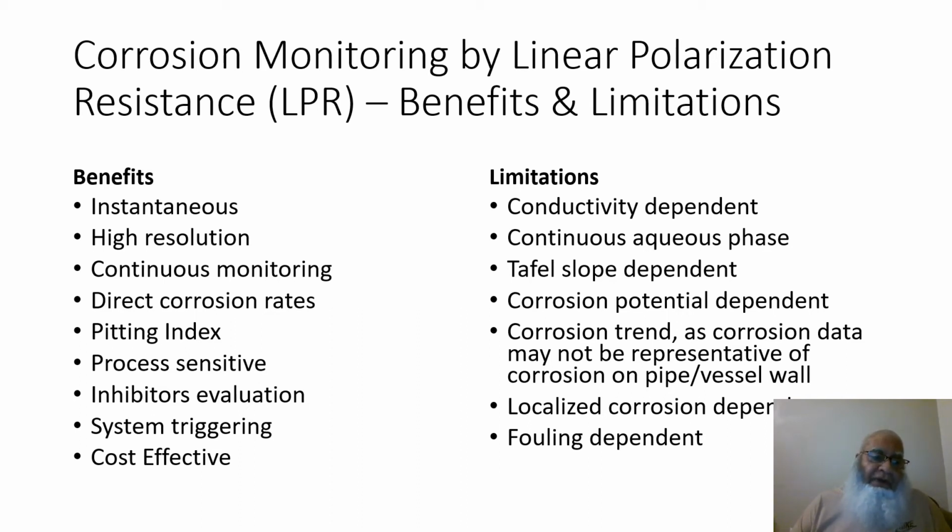It is cost effective. Its limitations: it is conductivity dependent, meaning the system cannot be used in gases or in non-conducting systems like ER. It needs a continuous aqueous phase, so the entire surface of the probes has to be immersed in the liquid.